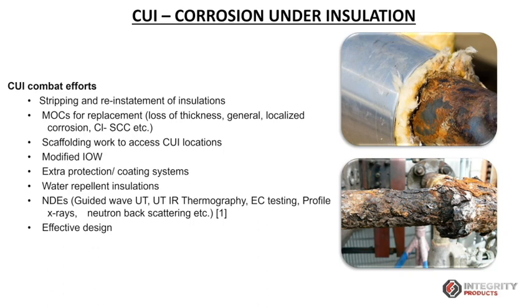I mentioned the concept of integrity operating windows. If we have to run a system at a lower temperature and lower pressure than what is expected, that means there is a loss of productivity, the production rate is less, and the quality can be compromised. So again, there is a financial loss. But even so, we modify that to keep within the safe operating limit, and we also go with extra protection and coating systems.